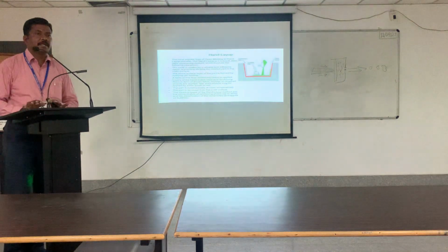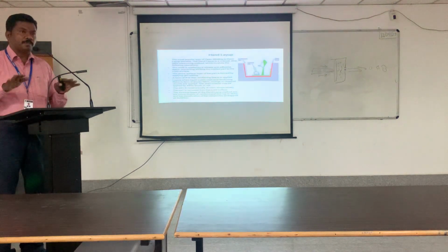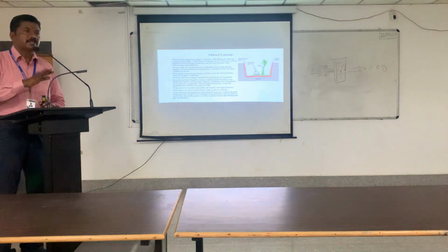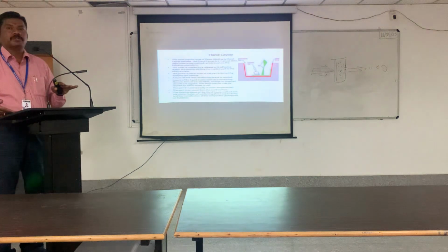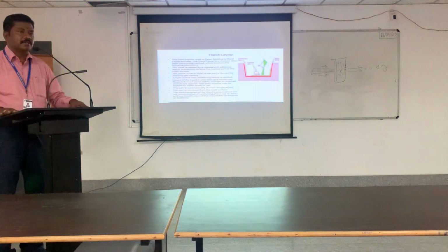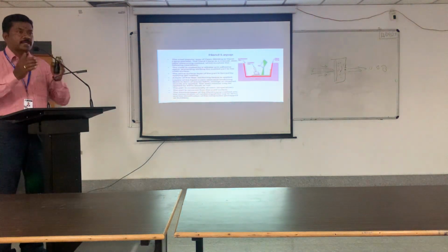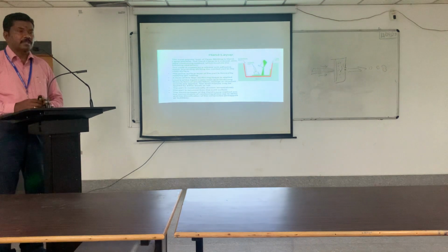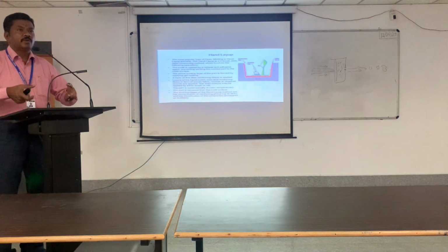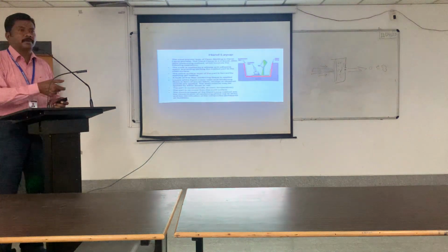Once you have completely stacked all the 10 layers, then on top of it a non-sticking film, similar to that which we have placed on the bottom, we have to place at the top. Then a plate similar to the bottom plate has to be placed on the top. Then you can place some amount of counterweight, to give some amount of uniform pressure, uniform pressure in such a way that 10 mm will be uniformly maintained.